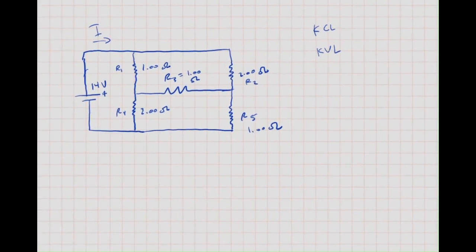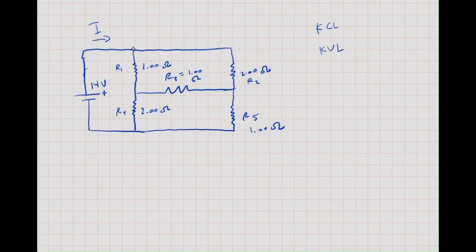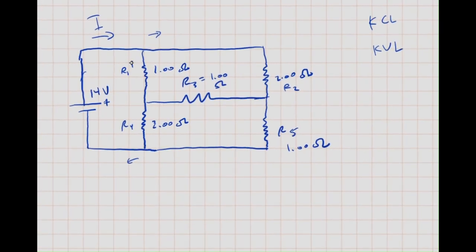So we'll start with the current law. We know that at a junction, the current splits between these two, and eventually when they meet again, they add back up to the total current. So basically, the total current remains constant across this split. If we were to add these two splits together, they'd equal this current. And how we're going to use that here: for R1, we can just say there's a current of I1 passing through this, but then the current going this way will just be I minus I1.